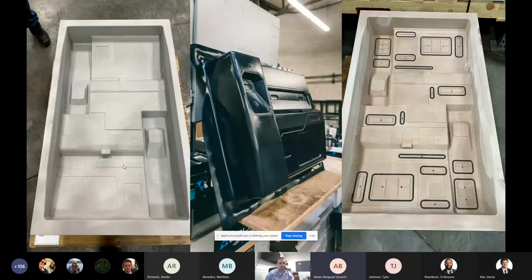It's then sent into the oven, and when it's heated to the right temperature, it's brought back over the mold. And then the mold goes up into the clamp frames. And once you create a seal around the edge, vacuum is then kicked on. And then if you have a good seal, the vacuum will pull the plastic all the way down.